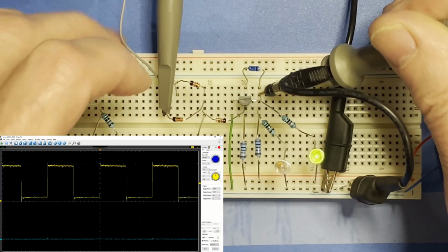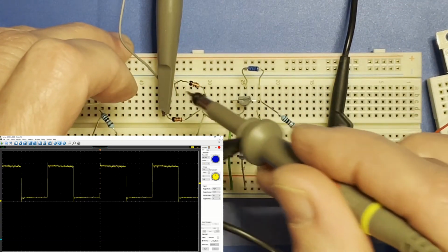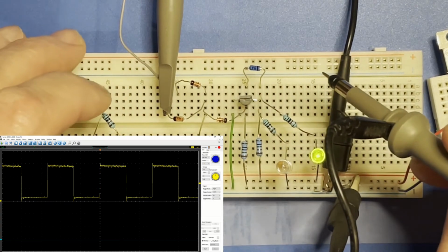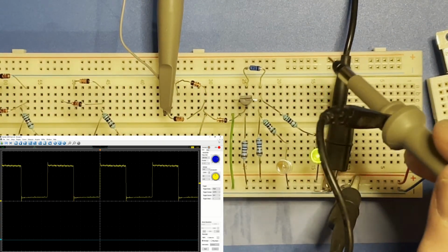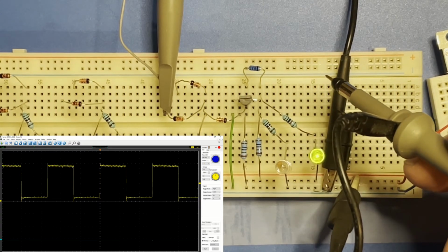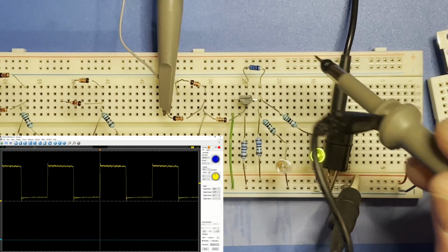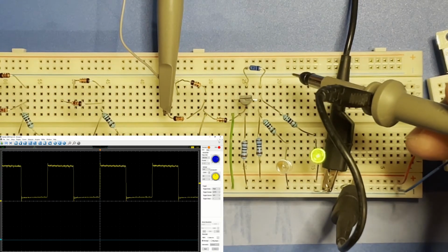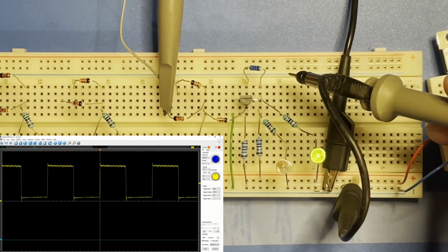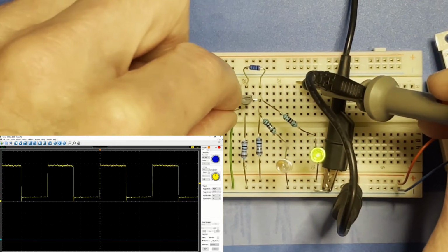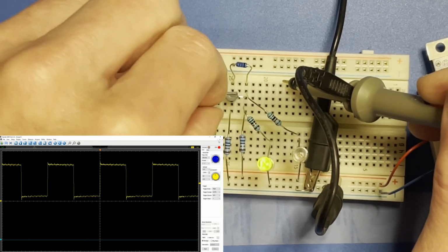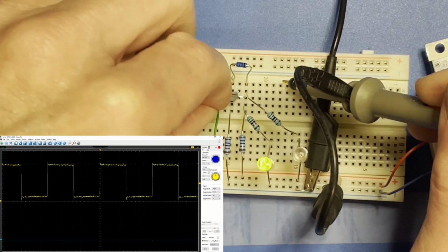Now the problem is that also that 0.6 volt, plus the logic levels, which you can see from the scope, the output of the oscillator doesn't go to completely zero, which is, as I said, normal. Things don't necessarily switch to theoretical levels in the real world; a lower level might not be quite zero. So the other fix is to put 2 diodes in series from the pull-up resistor to the base.